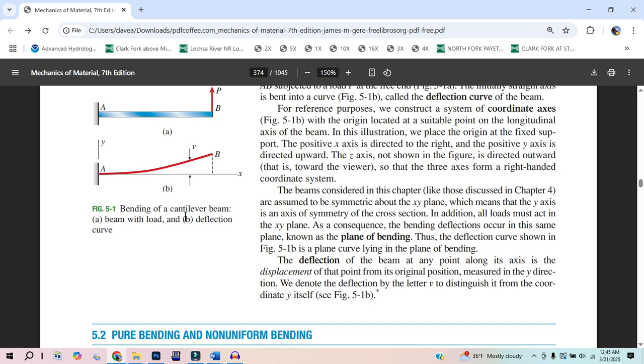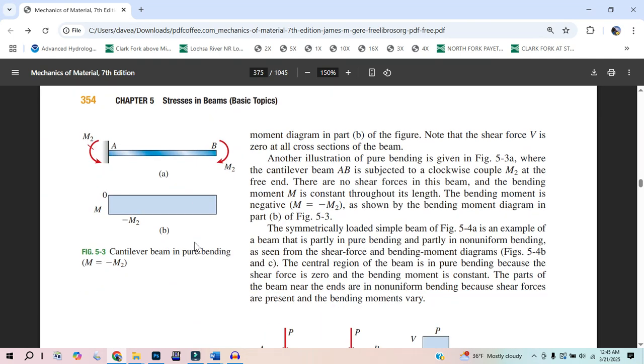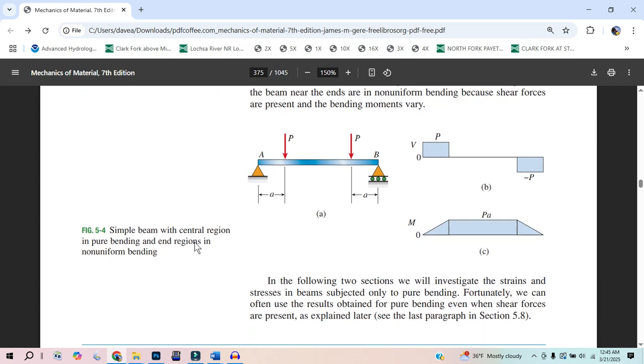That kind of rounds it out. It shows you that the presence of shear changes the moment. The moment started out positive, and as it moved, there was always shear, and the moment always changed. If you had a positive shear, that moment would increase. So that is a good place to bring it to a close.